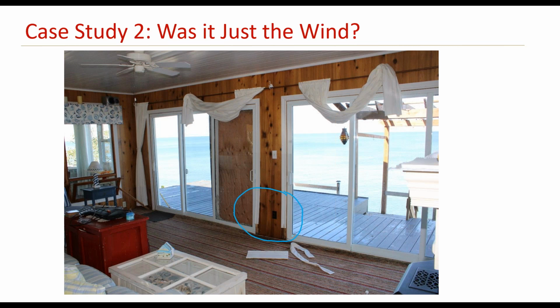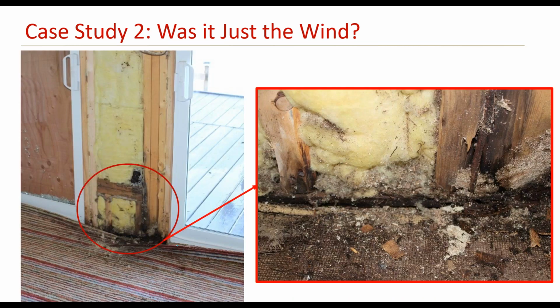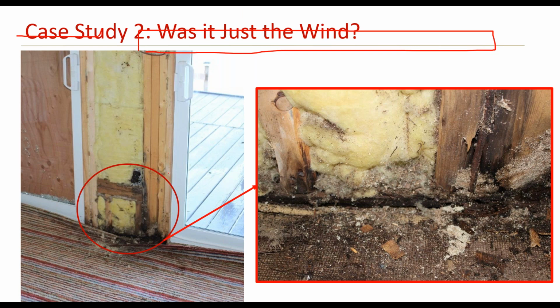We decided to remove the finishes to inspect whether we have any damage to the framing or to the sill plates. And to our surprise, there was a silent killer, slowly but surely deteriorating our structural members here. What happened is water was seeping in through this location and accumulating around the sill plate and the bearing parts of the stud posts. And we should note that on top of this stud post, we had a beam that spanned through the opening, and another beam from the other side. These beams are carrying the roof structure. So you can imagine how bad the situation would be if this collapsed.